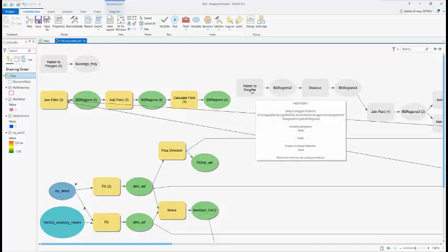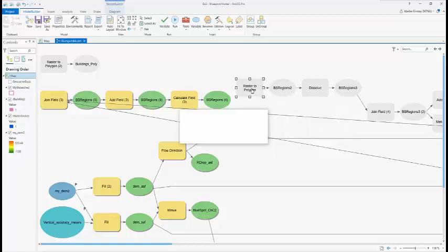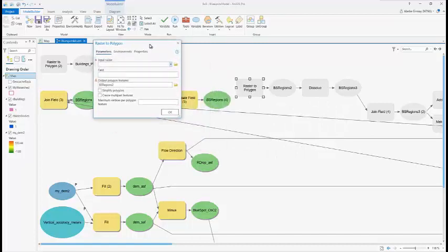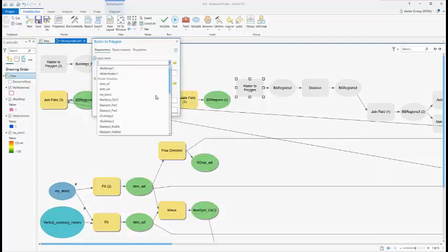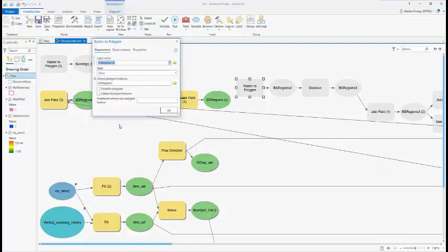Then the next step is the raster to polygon tool, and here this is the tool. If I open it, we want to convert the blue spot regions, because they are in raster, into polygons. The input will be the latest blue spot region we have, which is blue spot region number 4, here BS3 number 4.